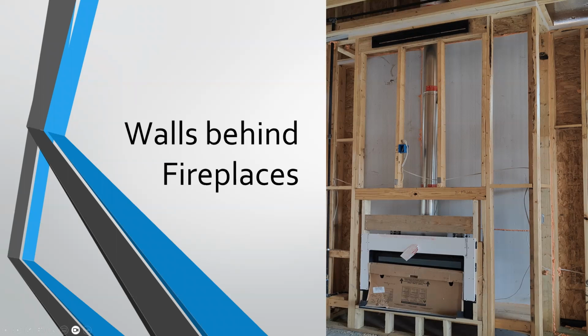The top is capped here. This was done as it was being built. The air barrier is complete. The insulation, which I confirmed was behind the T-ply that was here, is completely encapsulated. All the gaps, even on the sides of the framing, have been poly sealed. All the holes penetrating through that have been sealed, just like you would anything else on an exterior wall. They've done it correctly, which means everything in front of that no longer matters.